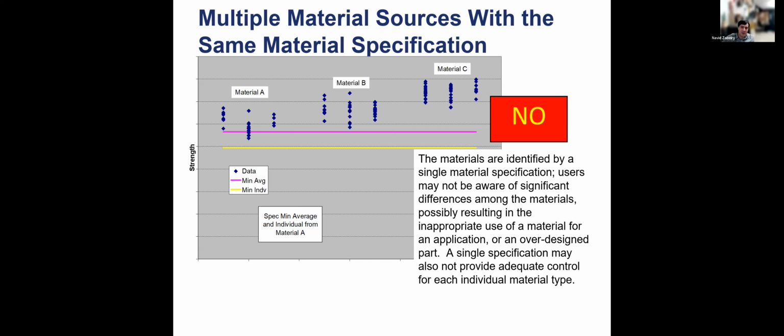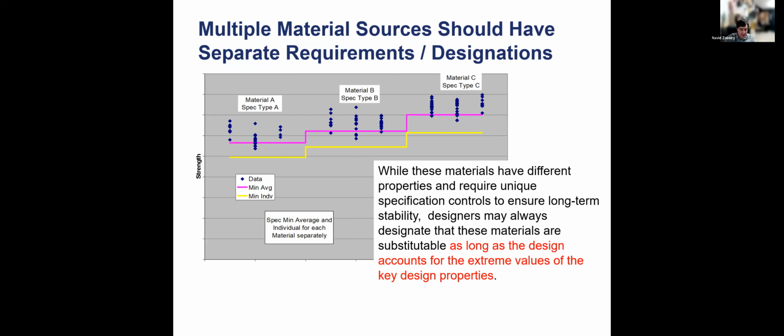And again, it's not sufficient to say material C is stronger than B and B is stronger than A, therefore it's okay to have the same sets of properties for all of them. As I mentioned, you have competing failure mechanisms in composites, and it's a very dangerous path to assume a material which is stronger than other materials is better. So it's not a good approach to assume that since they all satisfy minimum requirements from the process specification, they're therefore the same material. The correct way is to do something like this: even though they are all mature materials, let's say they're coming from different vendors, their minimum values are a bit different. Therefore, you will have different design allowables for each material. Even though they're all satisfying process specs, even though they're all under the name of the same material, they will not have the same statistical design value at the end of the day.